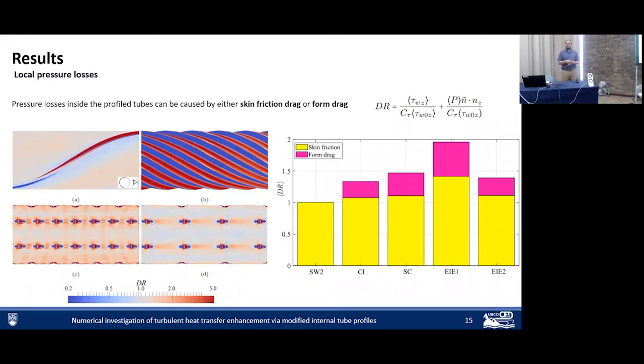That corresponds to, if you like, on an airplane, the form drag, essentially, the forces that are in the axial direction by these little structures that are sticking up and being in the way. You stick your hand out the window, that's the pressure you would feel. And the bars show the relative contributions of the skin friction and the form drag.